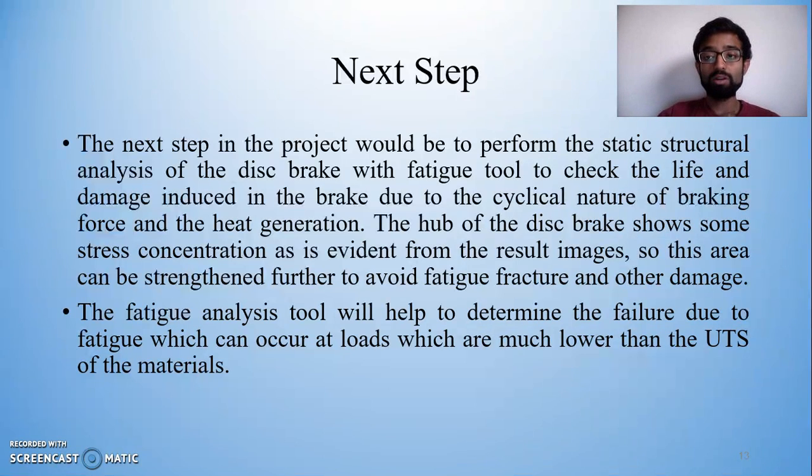As you can see from the stress contours, the hub of the brakes shows the real concentration of stress. So I think this area can be further strengthened to avoid fatigue fracture and other damages. The fatigue analysis tool will help to determine the failure due to the fatigue, which can occur at loads which are much lower than the ultimate tensile stress of the material.